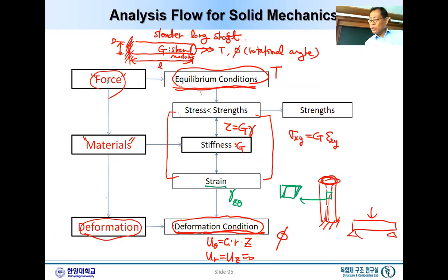You know, the shear is changing the angle, and that is d phi dz, which is constant, times R. So this is a constant, and you can see that the shear strain gamma is proportional to R. This is a center line here.